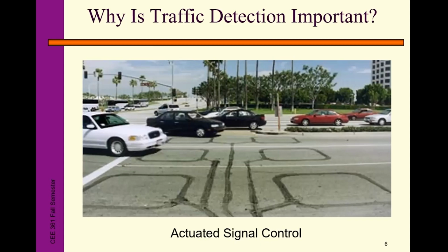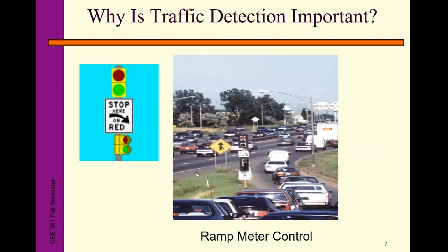We have the inductance loop sensors deployed, and when traffic occupies those sensors, it triggers an inductance change, and eventually the controller takes the input from the detectors, and then adjusts the signal timing plan accordingly and optimizes the traffic operation.